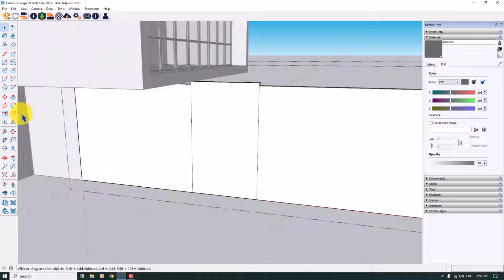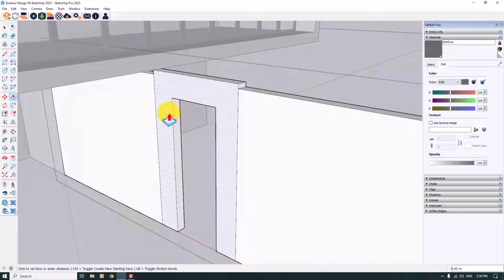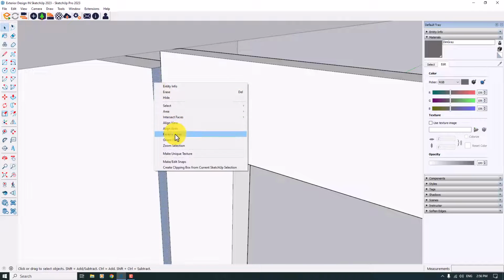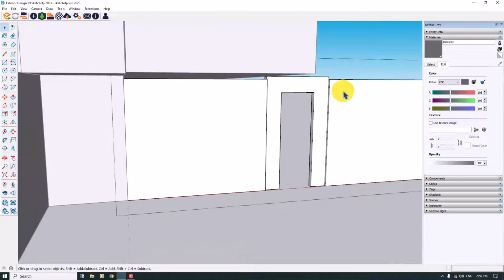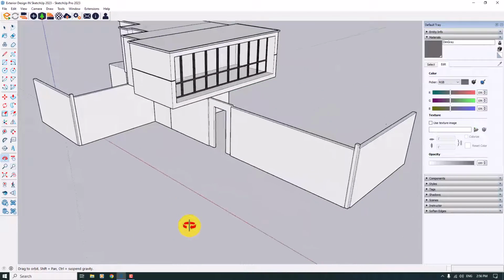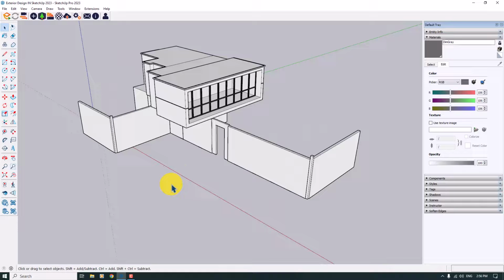And I want to use the Offset tool, very simple and easy. Offset and create my door, about 47 centimeter in offset. As you can see, now I can Pro Boolean, very simple, and move this part of my door a little bit to the back side, about 6 centimeter, right click, reverse face, and everything is done. So I think it's good right now, and I only want to create my road and my path.